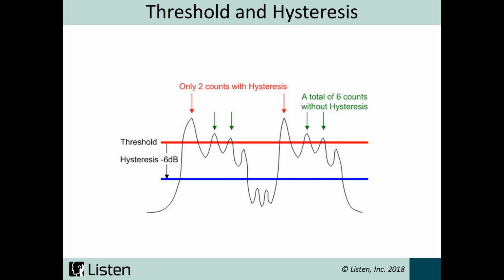This threshold must be defined and set high enough to exclude random background noise. Using a good known speaker, you can choose a level above the background noise, and then measuring a loudspeaker with known loose particles can verify that the threshold is actually exceeded.